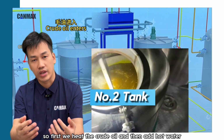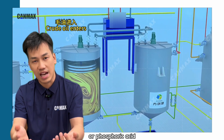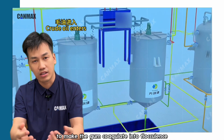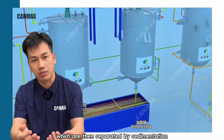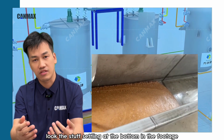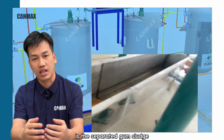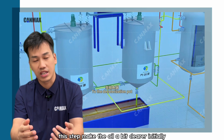So first, we heat the crude oil and then add hot water or phosphoric acid to make the gum coagulate into flocculants, which are then separated by sedimentation. Look, the stuff settling at the bottom in the footage is the separated gum sludge. This step makes the oil a bit clearer initially.